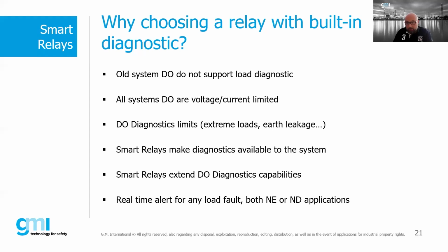We also must mention that in some other cases, the diagnostic of the digital output card is limited, and for instance, earth leakage may not be detected, or extreme load such as beacons may always be seen as an open circuit, which is an issue that can be overcome by using a safety relay. So as I just said, a safety relay can introduce the diagnostic feature when it's not present, extend it or enhance it when already available on a digital output card.